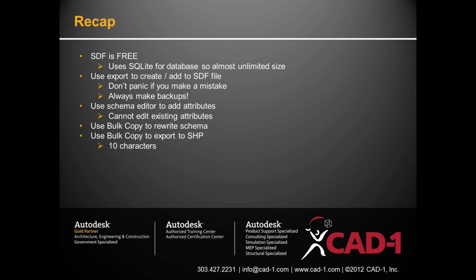Use bulk copy to rewrite your schema or to export it to a shapefile. Just the most important thing about the shapefile to remember, everyone: 10 characters, no spaces. And that's for the names, not for the values of the attributes.